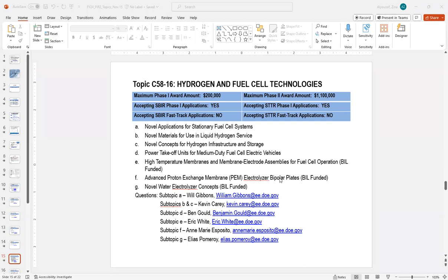Hi, I'm Anne Marie. I work in the hydrogen production sub-team of HFTO, and my topic is advanced proton exchange membrane electrolyzer bipolar plates. For this topic, we're looking for applications that develop platinum group metal free coatings for bipolar plates and/or develop bipolar plates that use materials that are less expensive than titanium, which is currently required for the conditions that proton exchange membrane electrolyzers operate at today, which include low pH, oxidizing voltages, and elevated temperatures.